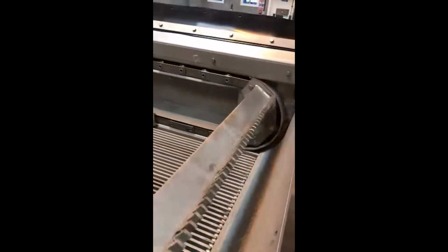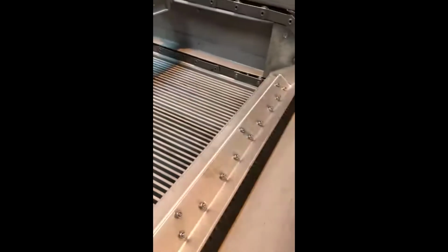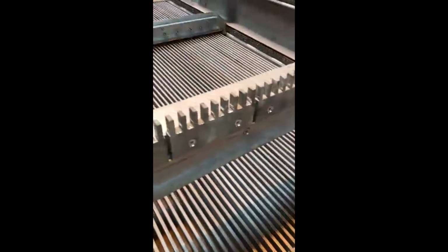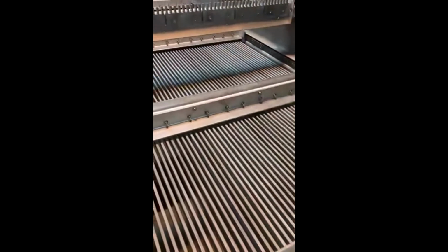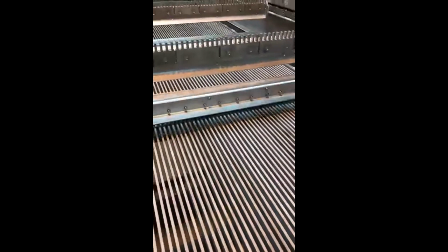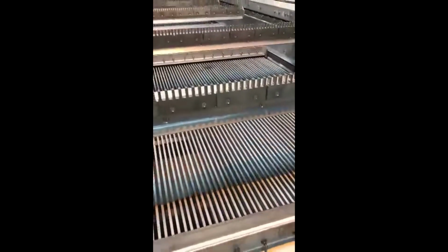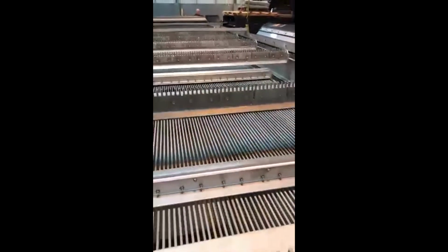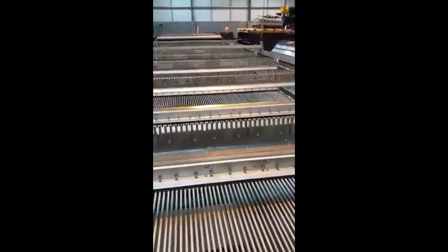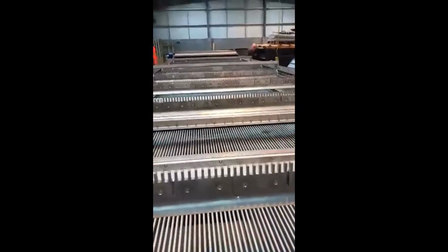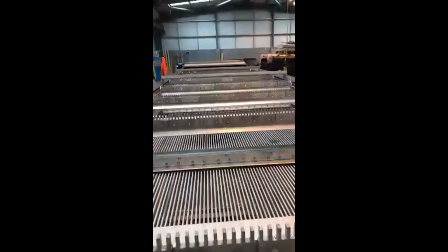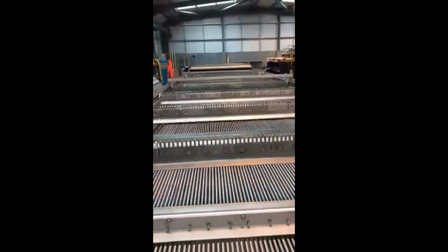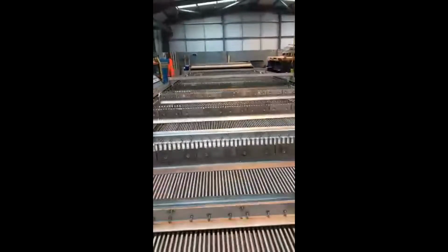So the flow is coming from top to bottom, if you like, through. And then the debris will collect on the grid bars, and these carrier beams will then remove that debris and take it to the top of the screen for discharge into screenings handling. So as you can see, a very nice, robust, solid design. The bars are usually tapered so that they're wider at the front than at the back. This just prevents any debris locking on the carrier combs as the combs pass through. So it just provides effective cleaning.